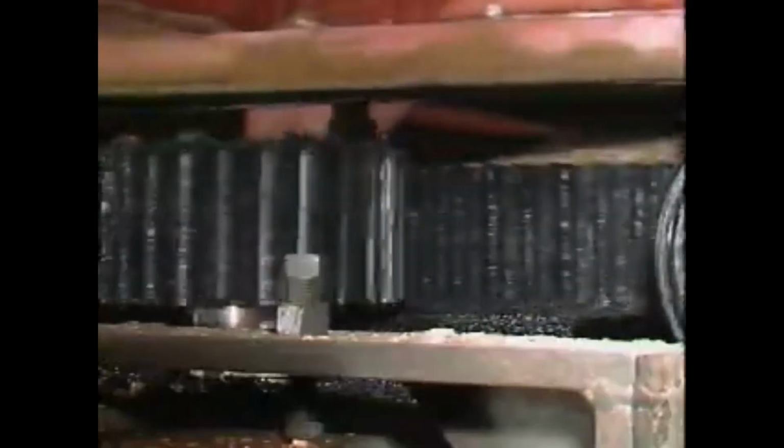An application with relatively high pressure requires a lubricant that won't flow away from where it's needed when the pressure increases, such as when gear teeth mesh. Applications that involve relatively high loads or pressures typically require greases, solid lubricants, or high viscosity oils. Speed is also a factor in lubricant selection because there's a higher rate of wear at high speeds than at low speeds.